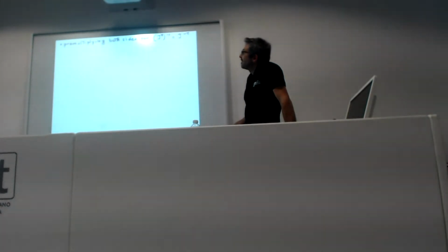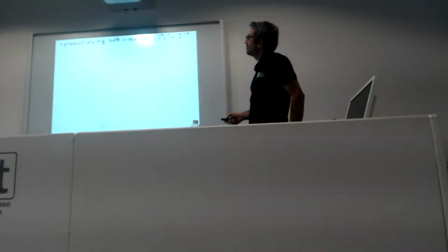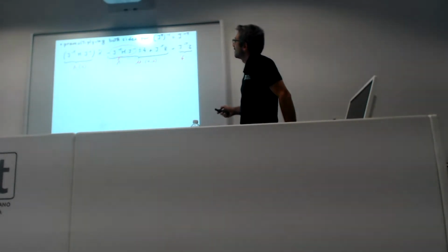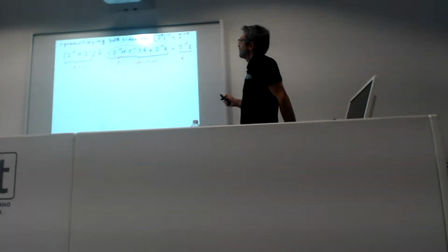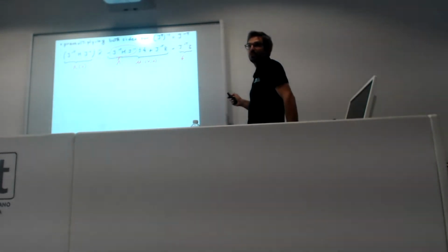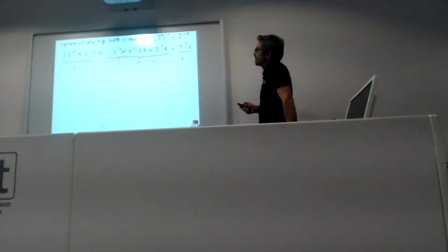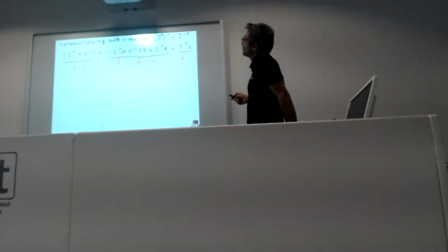Then we pre-multiply both sides by J minus transpose, and in essence the torque becomes a force, because this is the virtual work equation that says that the torque is equal to J transpose the force vector.